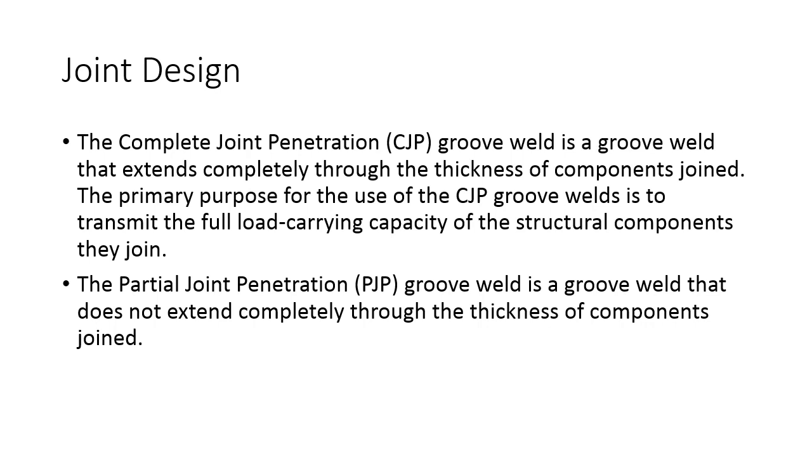I'm not a structural engineer. I have a cursory knowledge of the joint designs and when you'd use a CJP and a PJP, but when they are called out, you have to follow what's called out on the drawing. And in doing so, many times you can use a pre-qualified procedure if those configurations called out on a drawing fit up with the pre-qualified weld procedure that you've put together.